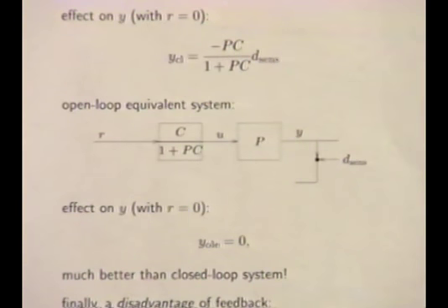The open loop one works just fine because it doesn't have a thermocouple to go wrong. The closed loop one, if it starts giving you the wrong sensor signal, it's going to start making corrections to the power and all that kind of stuff based on a totally wrong signal. And of course, it's going to have an effect that's going to induce an error. So that's a